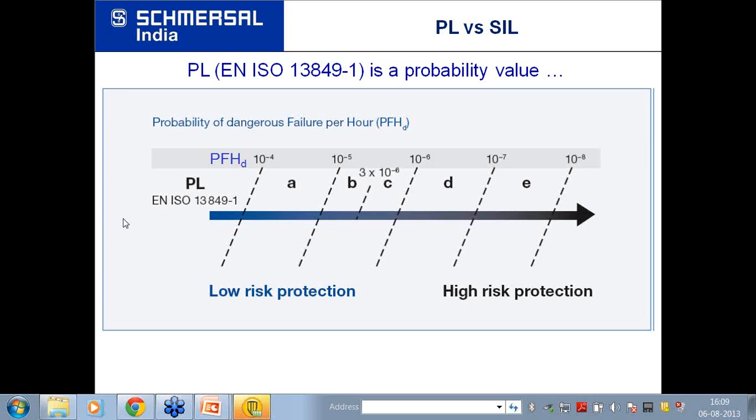But other than that, we don't have any other symbol by which you can identify that this is a safety compliant device. The way we can identify a safety device which is compliant to the standards or to the requirements is by going through its data sheet. All the manufacturers should write and give information about adherence to standards like 13849-1 or any other standard in the safety compliant standards. So there's no other symbol which I can tell you now.